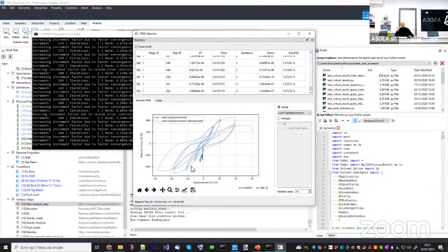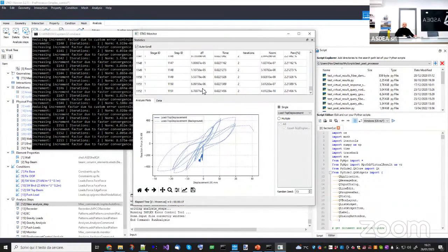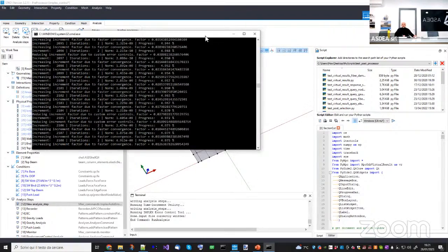Of course, it will take a little bit more than the standard IMPL-EX algorithm, but if you are not very familiar with the IMPL-EX algorithm, it will try to reduce the time step to avoid a huge error. So the advantage is that it will converge because it is IMPL-EX, but you will be able to keep the error under control. The price will be that the duration of the analysis will be a little bit more, okay? And that's it, basically.